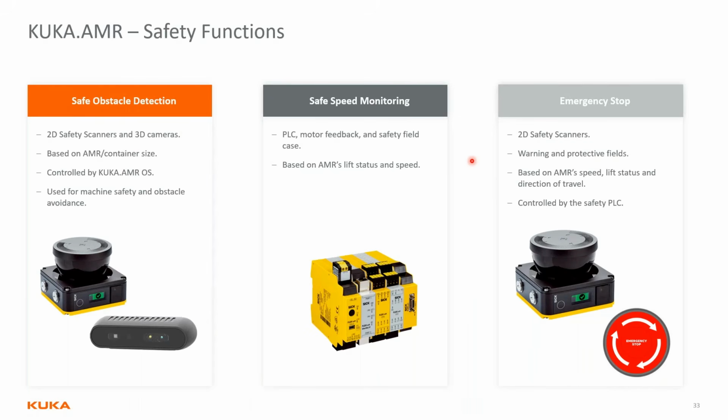Thank you. Someone said that they have an AMR with a top plate and one without a top plate. They both share the same path. How can I change the default OBS plan for specific AMRs? Very good question. When you change the AMR size on KUKA AMR suite, you're changing the AMR size per vehicle. So each AMR can have a different size.